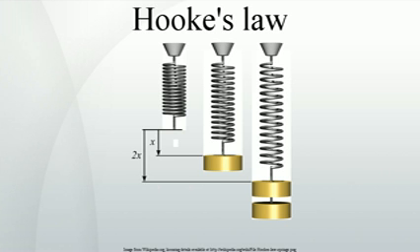For a linear elastic material, the quantity is a linear function of the strain, and can therefore be expressed as, where the coefficient is a fourth-rank tensor of material constants, also called the stiffness tensor. We can see it must be a fourth-rank tensor by noting that, for a linear elastic material, in index notation. Clearly, the right-hand side constant requires 4 indices and is a fourth-rank quantity.